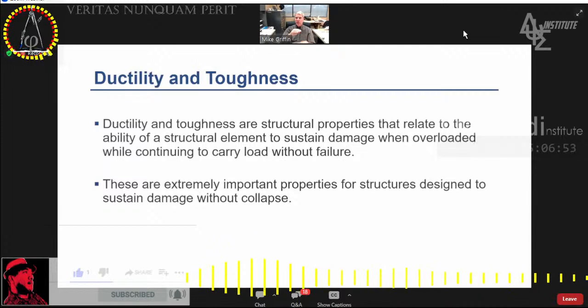But we also require for these high seismic shaking environments that our building maintain a level of ductility that's required by code, so that in case that maximum earthquake did occur, the building would undergo displacement, but has ductility to avoid collapse. That's how it's handled. Again, that's acceptable risk. So ductility is very, very important.